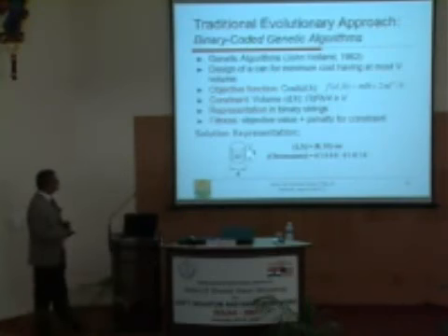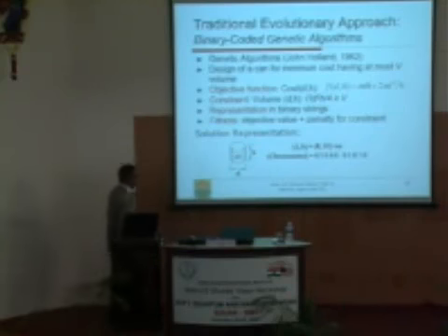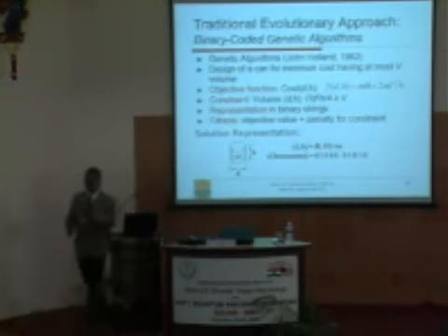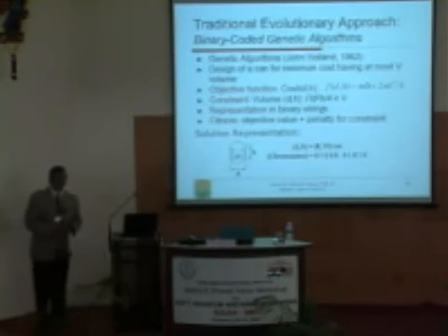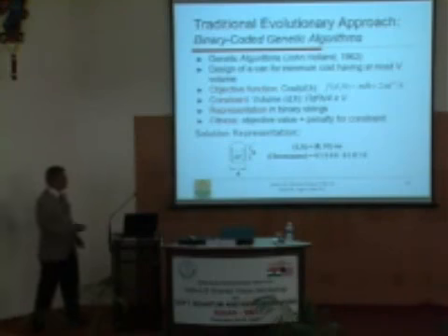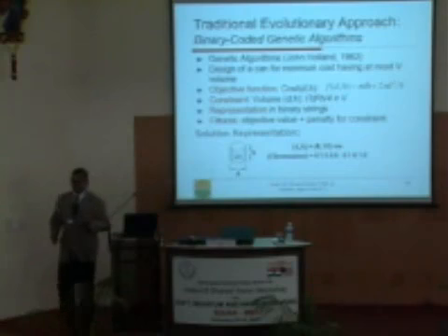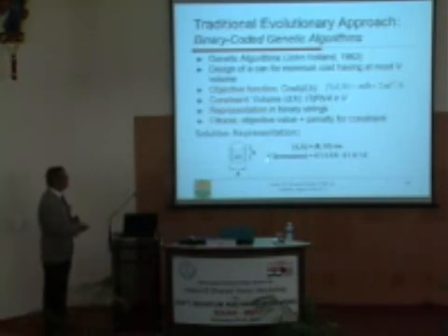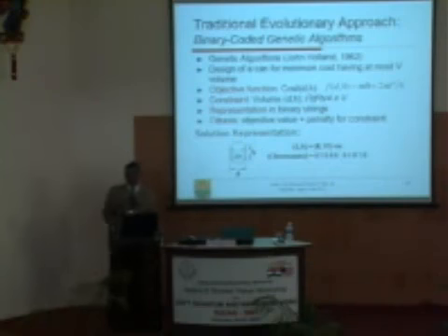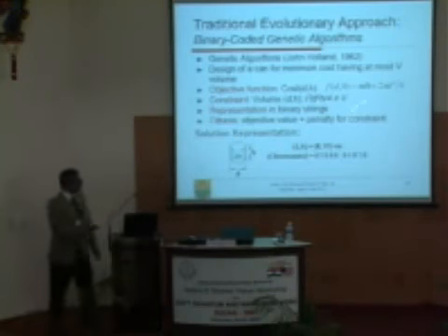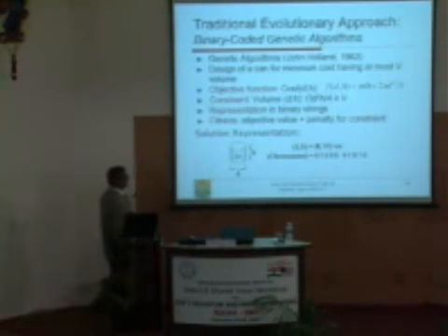Say you have a problem of designing a can, which has two variables basically, diameter and height, and you're trying to come up with what height I should have so that the overall cost of fabrication is minimum. Cost of fabrication can be related to the total surface area, because that much material you have to put in. So I have written it down in terms of diameter and height. And you can throw in a constraint saying I want the volume inside to be at least V, maybe 300 milliliters or something.